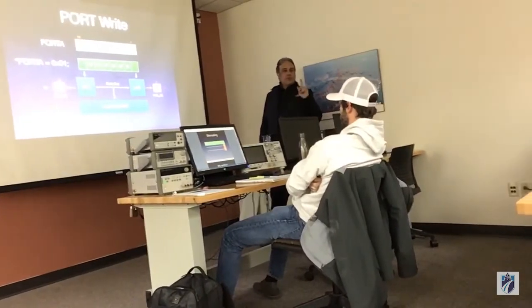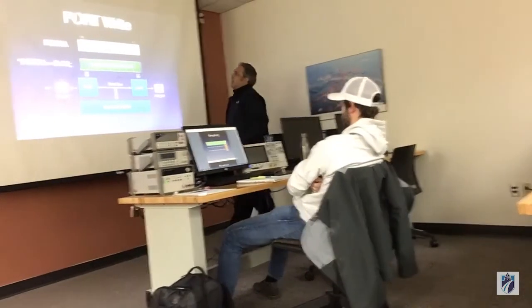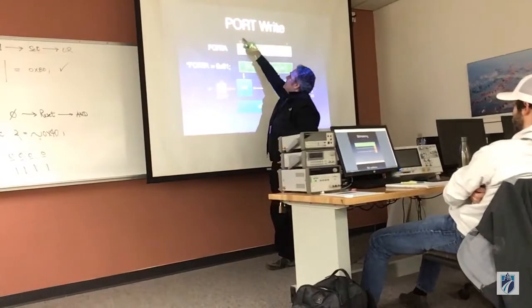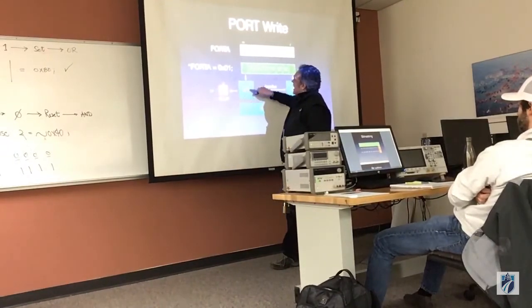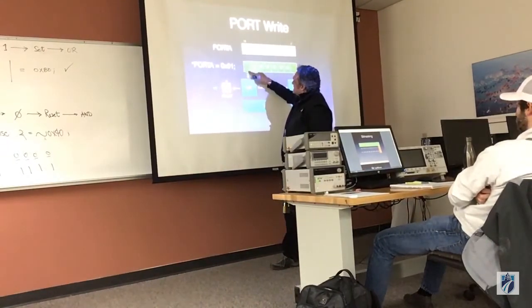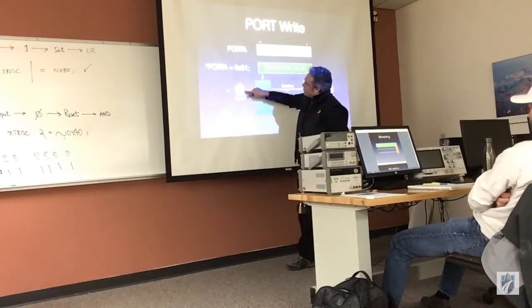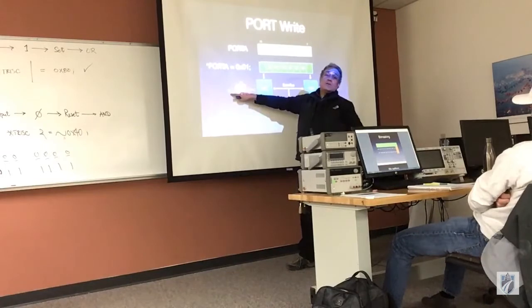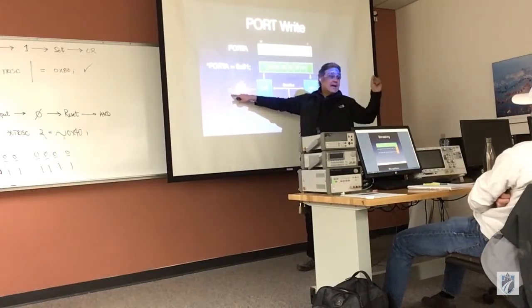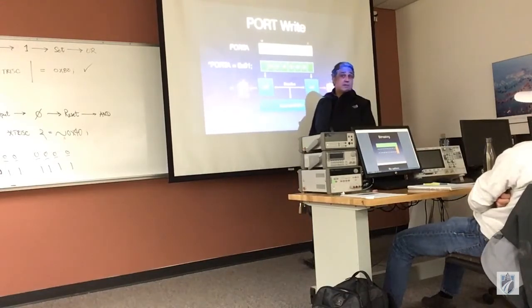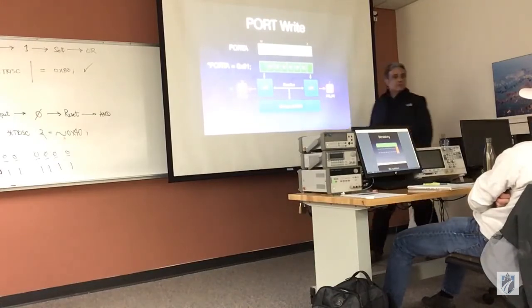What the system is doing is that when you write a 0 into the latch, the port sends the 0 to the latch, and the latch sends the 0 through the pin, and you actually experience 0 volts in the outside world for the first time. You can actually take a multimeter and look at it. See that?